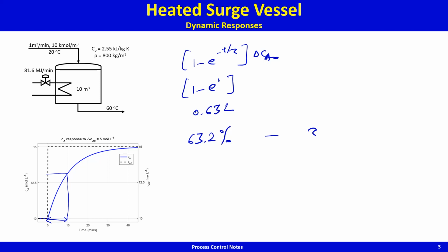You can do these calculations, and maybe I should have done it, but I have not. But just from memory, if you go two time constants, the response would be about 85% complete. If you go three time constants, the response would be about 95% complete, and so on and so forth. So that's a first order typical response.